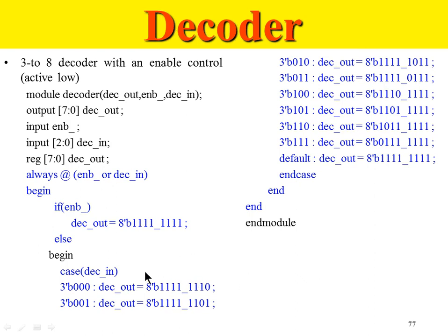So one change I would do in this design is, instead of blocking, I'll use non-blocking assignments. This is intended to be a design, so I would try to use non-blocking everywhere by default. The rule with blocking and non-blocking is that if you use non-blocking once, you have to use non-blocking throughout the design. So I will change all the blocking assignments to non-blocking assignments. That is one thing I would do to improve my Verilog coding, though it's not going to make any change in my result.